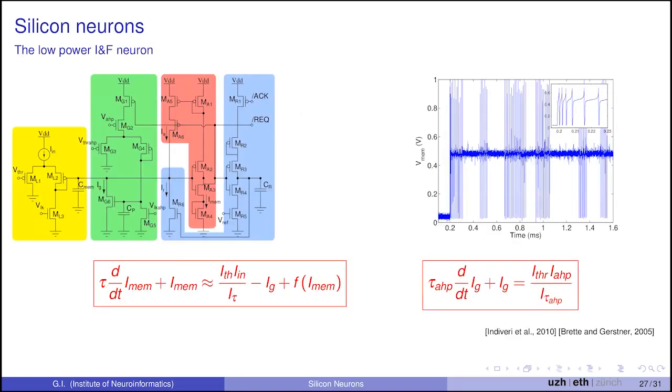And these circuits that I showed you are sort of state of the art. As I told you, it's a hot area of investigation. This was already done 10 years ago, but variants of these have been proposed even in the latest ISCAS 2020. So it's still a very hot topic. You have on your class chip this circuit and other variants of the circuit that you can measure from. You will also measure from the axon hillock circuit that is also on the chip. There's only one of those, so even though it burns power, it's not going to compromise the chip. So it's no problem if you keep it firing, even with very small currents.